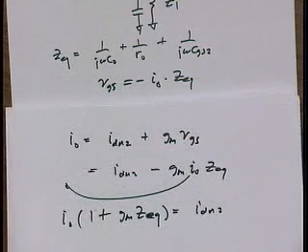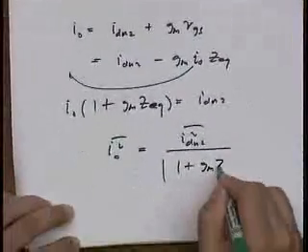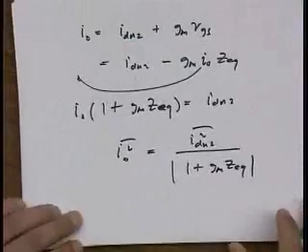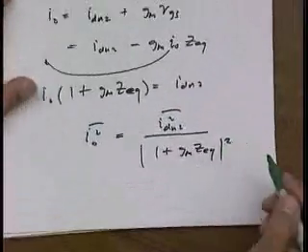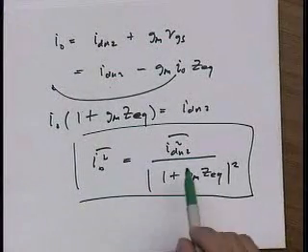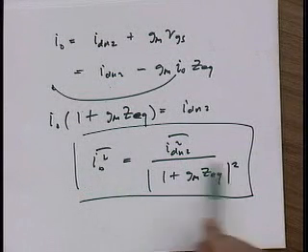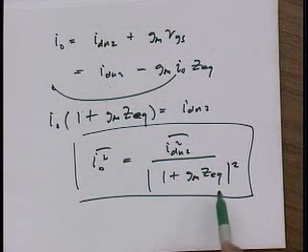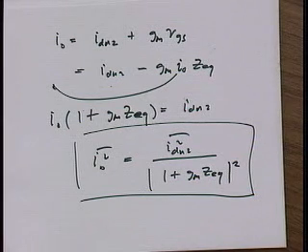In other words, the output noise due to the cascode transistor is suppressed by 1 plus GM Z equivalent squared. So this is the intuitive result: the reason the cascode noise is not contributing is because it's getting rejected by this factor. And clearly we want this to be large to reject the noise. Right? That makes sense to everybody?